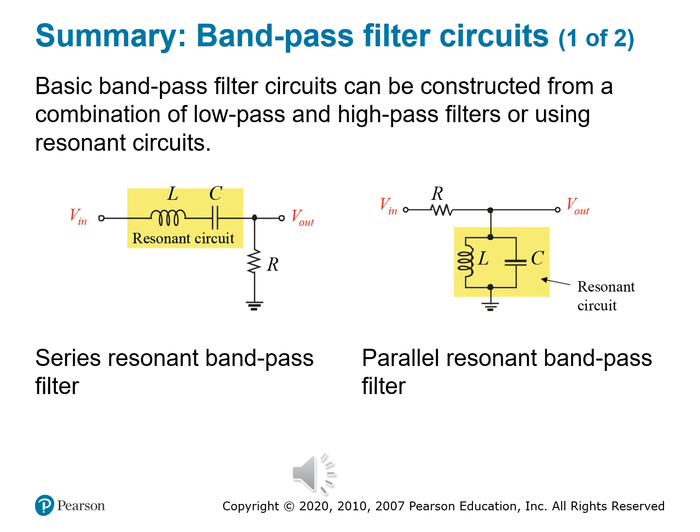And this is important if you're filtering RF channels, designing equalizers, or cleaning up sensor signals, bandpass filters are the way to go. So you have two types you see here, again, the series and parallel resonance. They both give you different tools for different use cases.